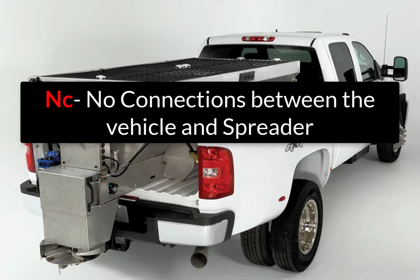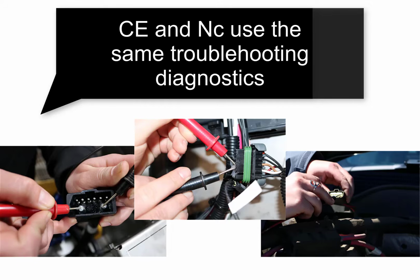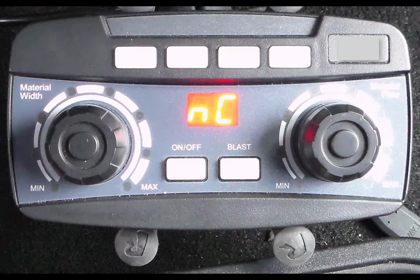The NC code indicates that there is no connection detected between the hopper and the vehicle. The CE code indicates that there is a communication error between the spreader module and the cab control. Although these two codes have small differences, they should be treated in the same manner. If the NC or CE code flashes on the cab control, the first thing you should check is your connections.